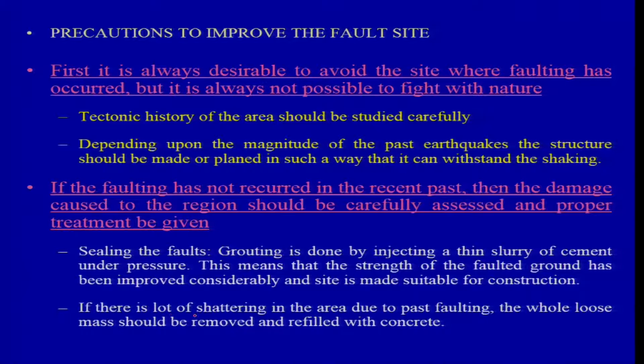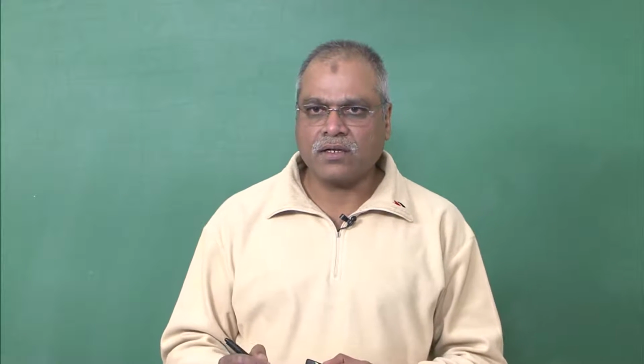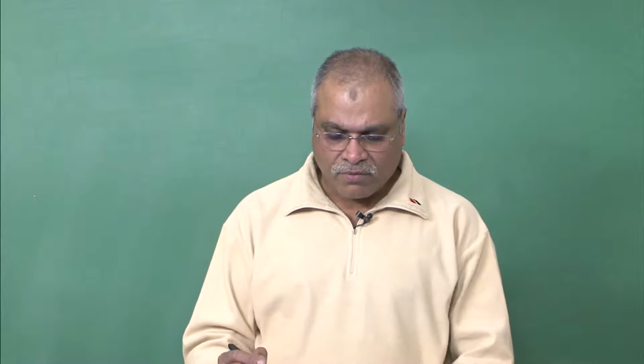So, if there is a lot of shattering in the area due to past faulting, the whole loose mass should be removed and refilled. If you have an old fault and you are doing that, then you can consider the concreting and grouting part. There is absolutely no problem for that.